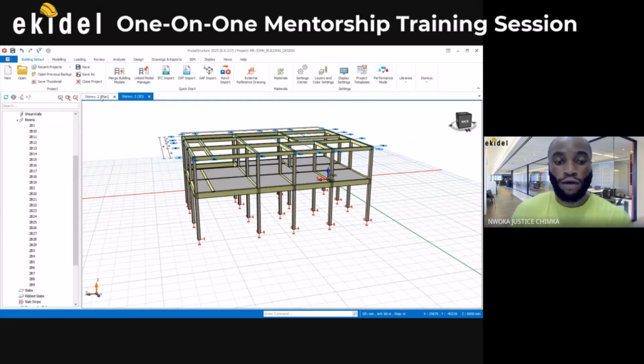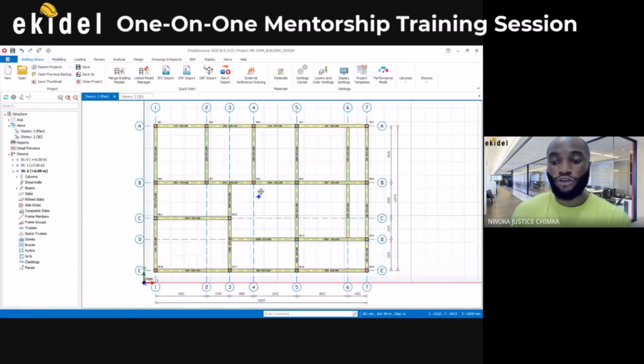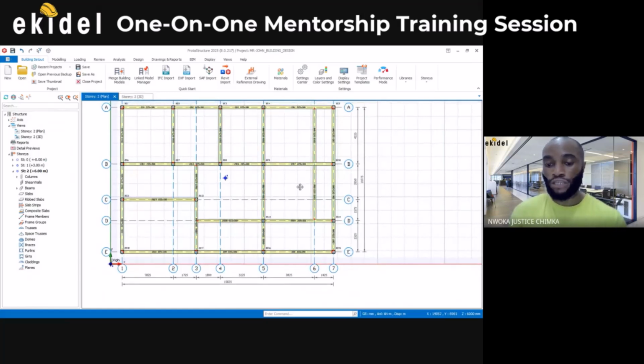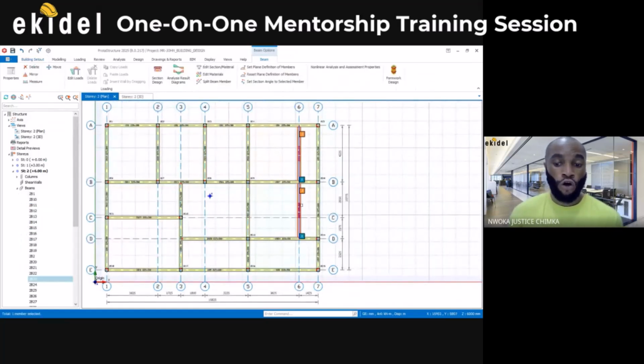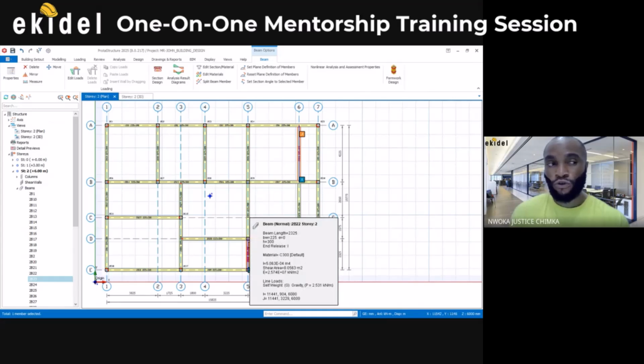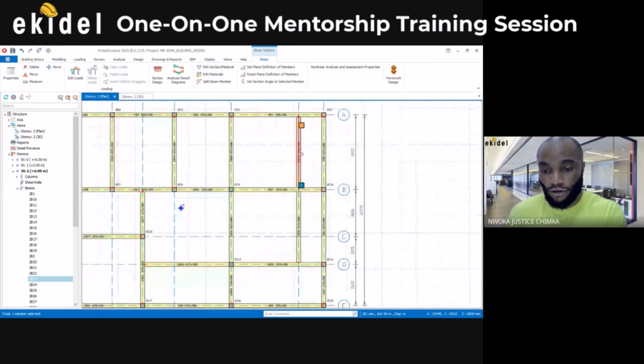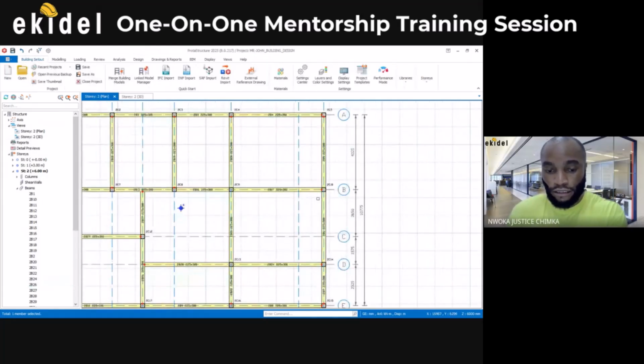Under your roof beam now, if you come to your story 2, you can choose to remove most of the beams. For example, this one here can be removed on the roof beam, just to save more cost, because we don't need this. You can choose to span our roofing wood, timbers or wood. So you can choose to delete this beam and then delete this one. We don't need that.